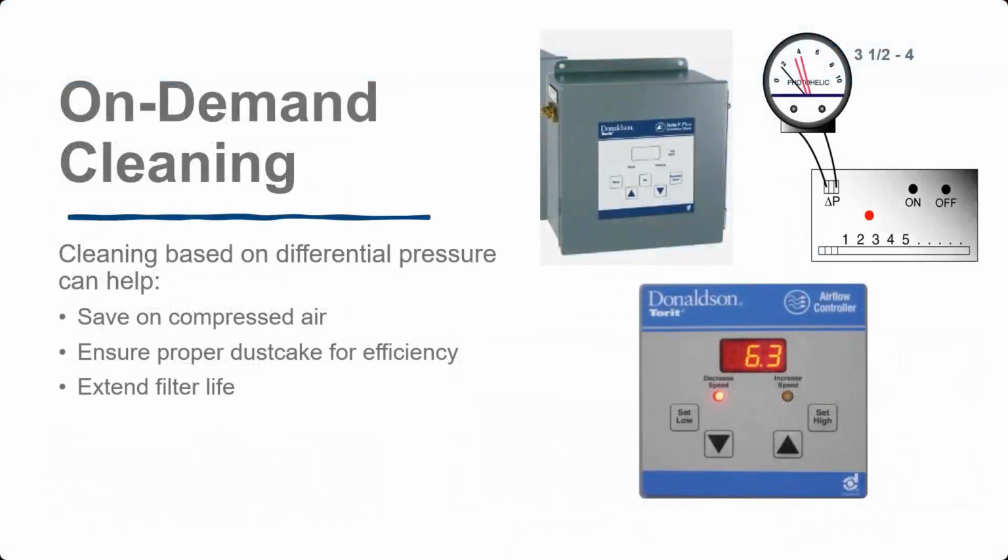And then I wanted to go back real quick and talk about depth filtration. A lot of people are going to stick with polyester bags because they're cheap. All these other things that I've talked about, the spunbond, the EPTFE membrane, they're going to be more expensive than your standard polyester felt bags. And sometimes the budget is the budget, right? Well, if you're going to use the standard polyester felt bags, the thing that I'm going to recommend the most is to make darn sure that you're cleaning those filters right.